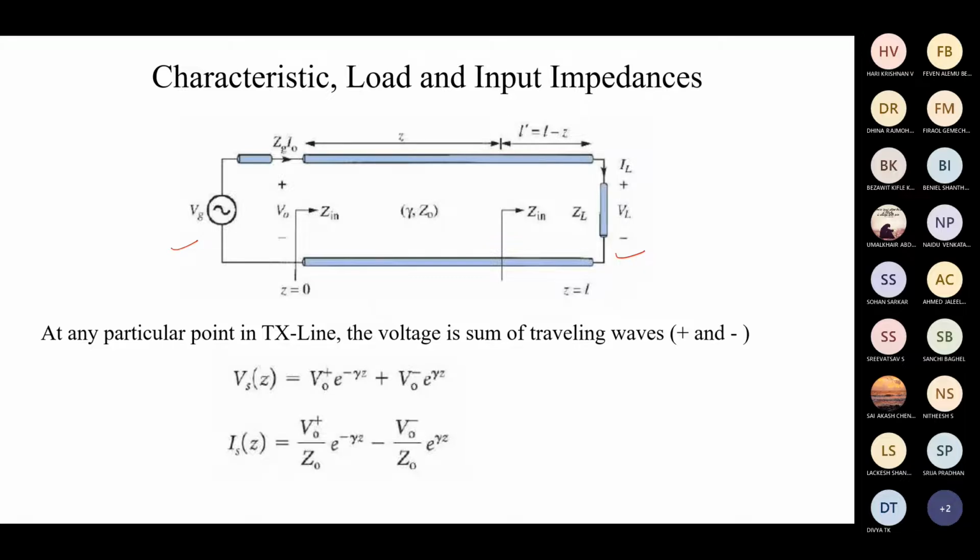Only after those frequencies will we see the reflections due to impedance mismatch, the wave traveling in a particular direction, and seeing the difference between the impedance of two different media. All these things are attributed only to high frequencies.